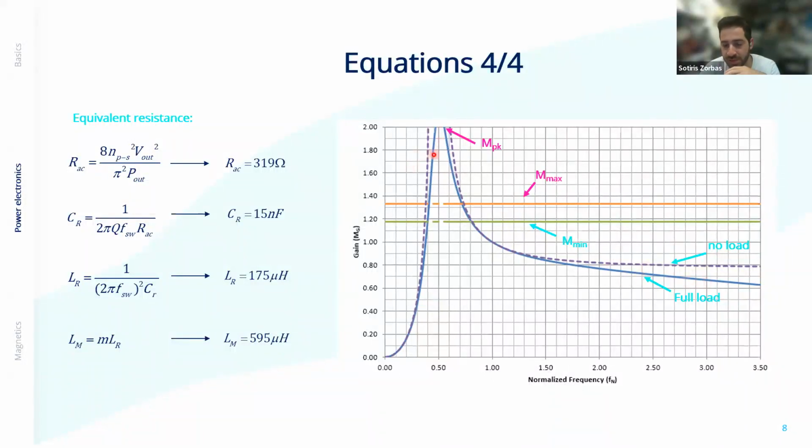And under full load, you can see that what we have selected here is also giving us a high gain value. So operating in this area is very doable. The goal is that under full load, this blue line should be higher than the highest gain that I need to get the voltage at the output. It's as simple as that.